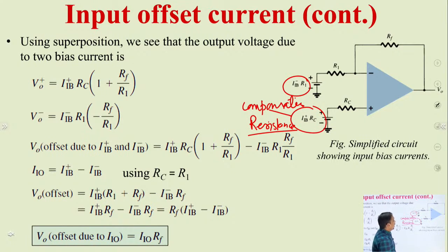As we can see, we again have two inputs, one is A and the other is input B. How can we analyze the circuit and calculate the output? Again we will utilize superposition. Superposition says that if we have two or more inputs, we consider one source at a time.